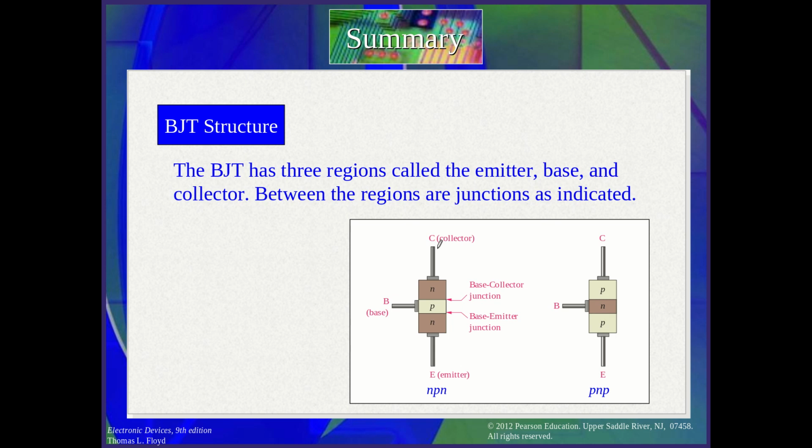And if you remember photodiodes, it is the same idea. It receives some light from outside, and then there is a current inside the diode. The phototransistor has more gain, and it is more sensitive to light than the photodiodes. In a typical circuit, the base is left open until there is light.